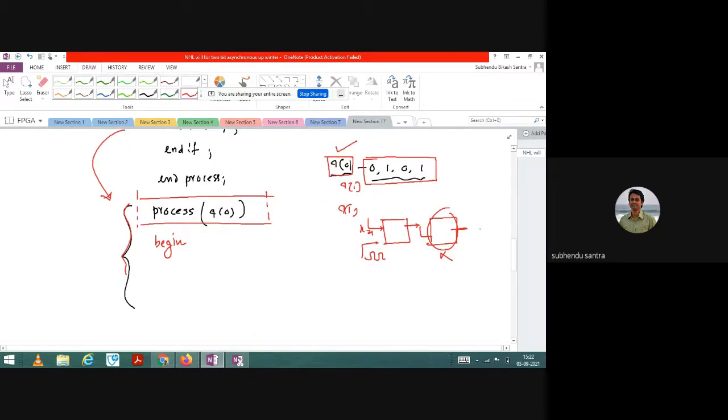And if you have more number of bits, then again you have to process this one by one. Because if you have, let us say, more number of flip flops, then the next will be depending upon this output. So once again you have to write the code which will be depending upon the output from this particular event. Okay, so this is called sequential way of writing the code. VHDL is inherently a parallel architecture, but if you write in this asynchronous way, you have to make sure that it is sequential. So first it will execute this, then it will go to this, and then to this.